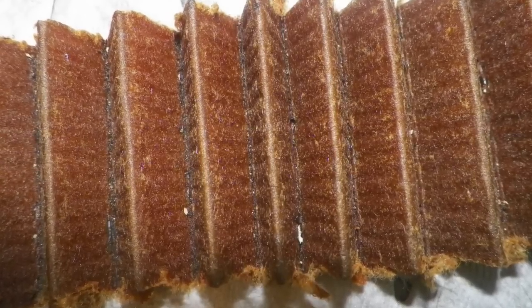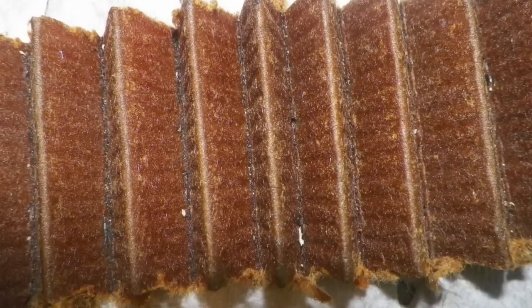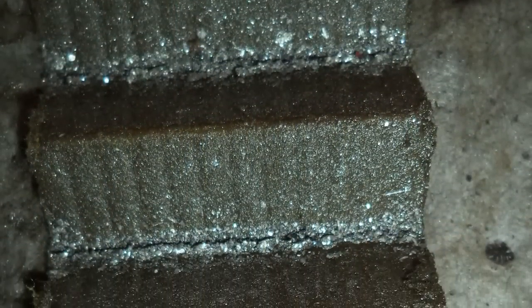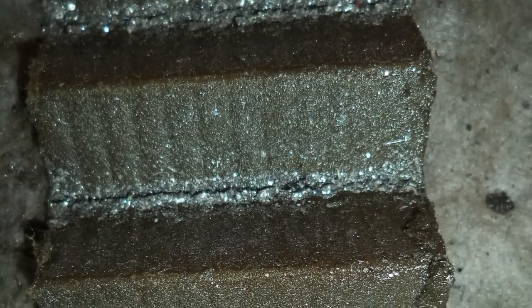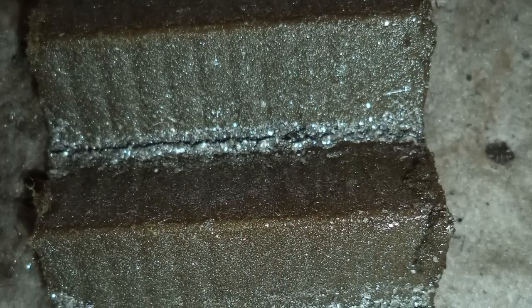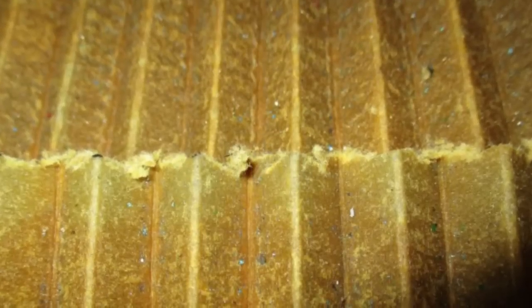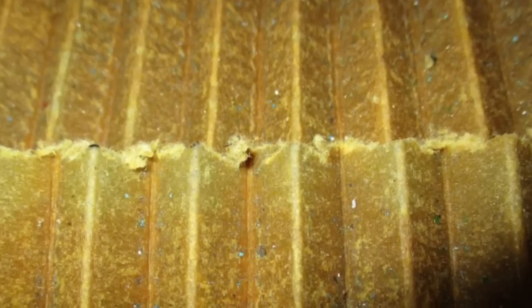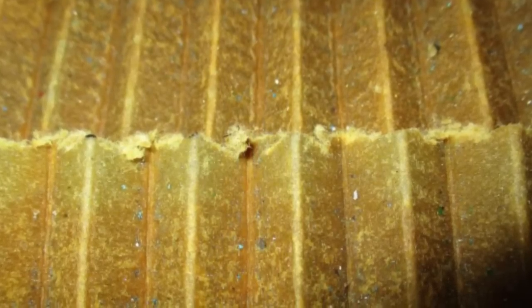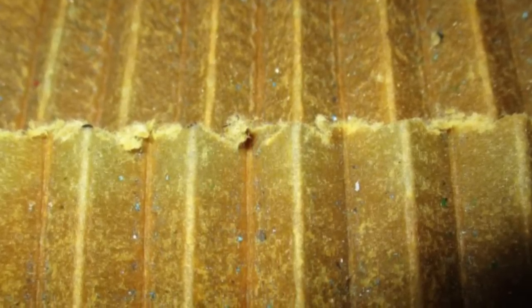One speck of metal doesn't mean an internal engine failure. However, a significant amount of metal in the filter could signify an internal engine issue. If you check the filter and find colored flecks similar to these, and you're working on a Ford remanufactured engine, there's no cause for concern.